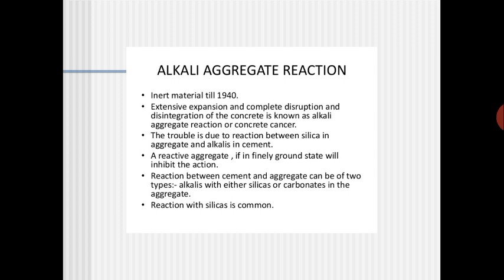Normally some carbonates will be there in the water as well as in the cement also. Sometimes this alkali is going to react with the carbonates or the alkali is going to react with the silica, but more commonly the alkali reacts with silica, because only a small percentage of carbonates is available.